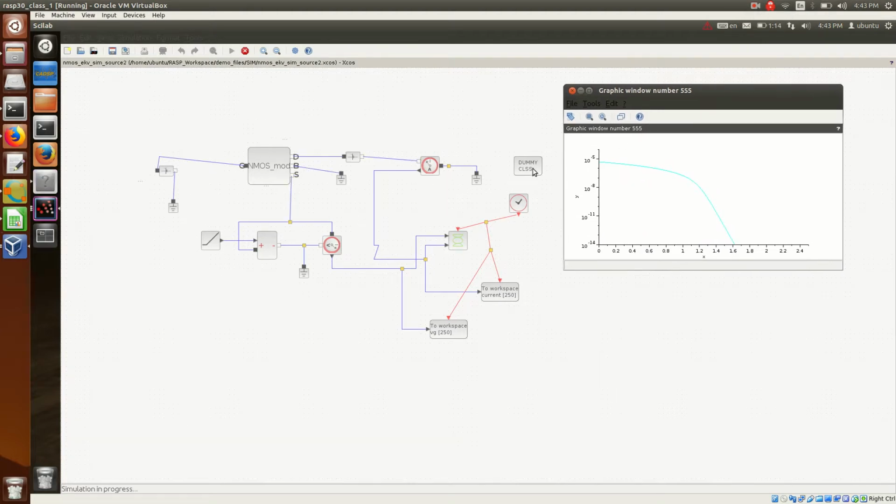And the last plot we did was we set up the source sweep. So once again, the gate we set to 0. This voltage source here is actually 0 volts. And we set the drain back to 2.4 volts, and the source was just set to this voltage sweep. And our data looks similar to the experimental data where we extracted the parameters from.